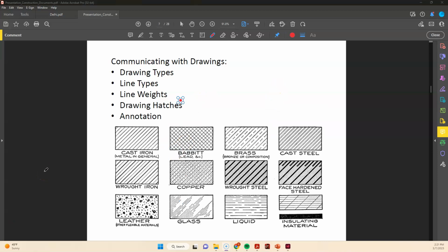Okay, our next tool is, or are, drawing hatches. So hatches, again, very specific, and hatches are different at times in both section and in plan or elevation. They could all be very different for that matter. So this, for instance, insulation, that's a rigid insulation hatch, which is in section, only in section, for instance. And these are metals, which we don't use as much in buildings. We don't zoom in and typically see metals that much.